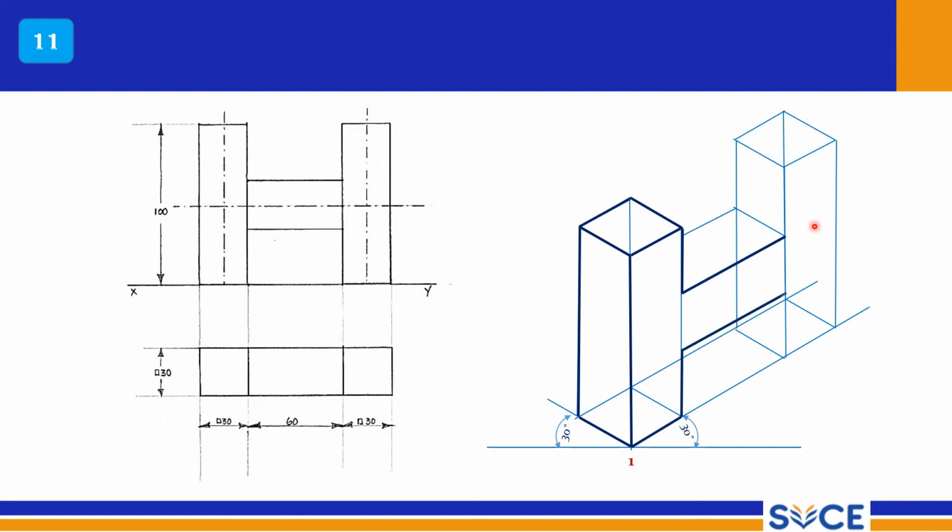Now from here to here thick line, and here to here thick line, and the remaining portion should be drawn with thick line. This is the vertical member, and this is the visible surface, right? Visible surface, and this should be drawn with thick line, right? Only this part, this much is visible.